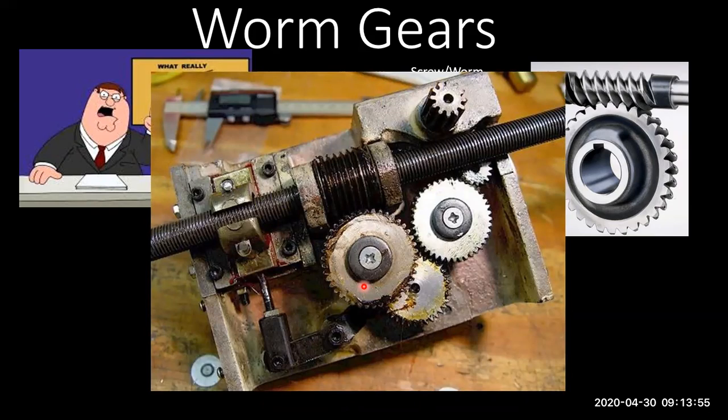This is, I think, a motorized kind of thing. It's the same mechanism. You can see this is for a lathe machine. You might have come across this in the lathe carriage, which moves. This is rigidly fixed on both ends. When you start rotating this, the whole lead screw of the lathe machine, which is housed in the worm, starts moving, and the whole carriage moves in the linear direction. So the lathe machine is one such application.